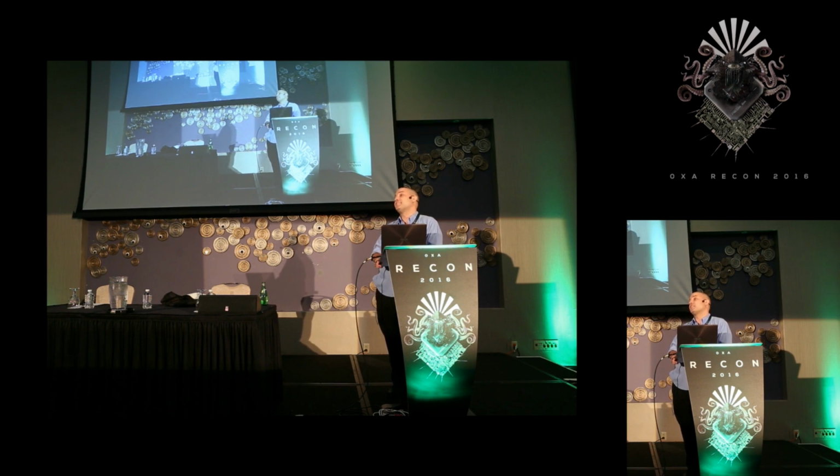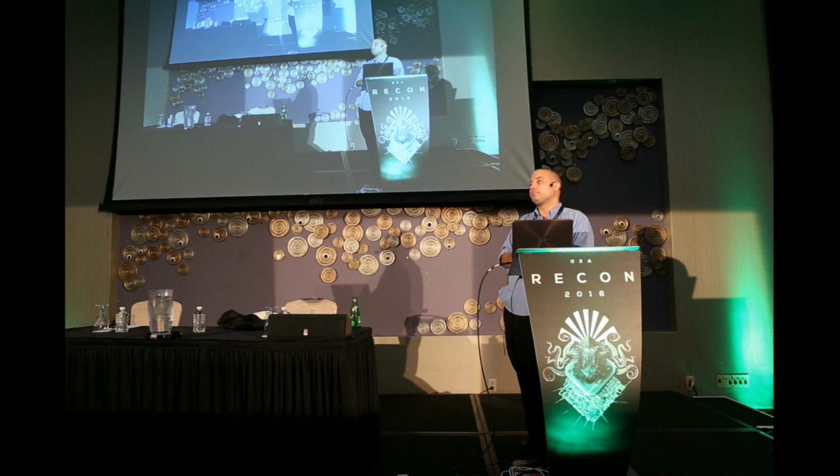The dead addresses actually didn't cause me any problem because when I was studying the software, I could see that they would read specifically from address 0, 1, 2, skip a byte, 4, 5, 6, 7. So this looked very unusual and tipped me off that there was something going on there. And then at the point when I actually had access to code inside of the chip, then I could poke around a little bit. But no, when those dead spots are hit, there's no bad reaction. It just resets the chip, so I didn't lose any to that.